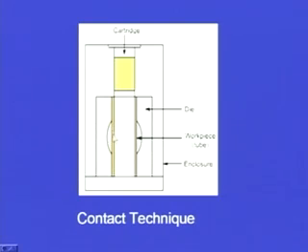This is a tube; we see that inside it is hollow. This tube will bulge from here. The die cavity has been made in such a way that we are going to create a bulge in the tube, so bulging will take place. In case of the contact technique, the cartridge is in direct contact with the raw material or the workpiece, and we can cause bulging in the tube using this process of explosive forming.